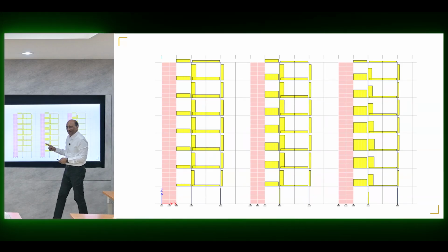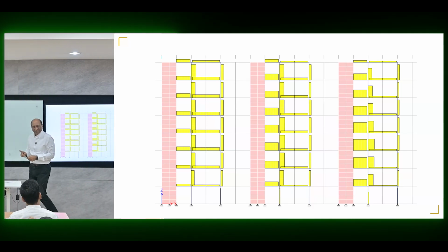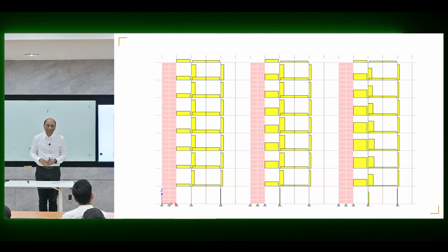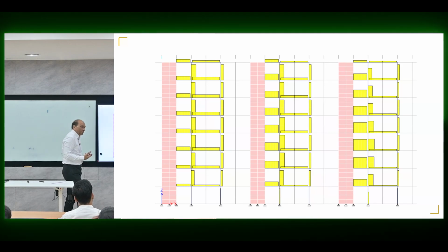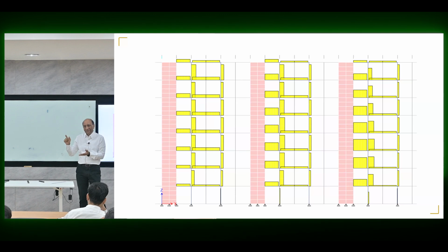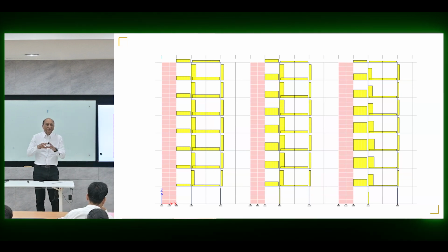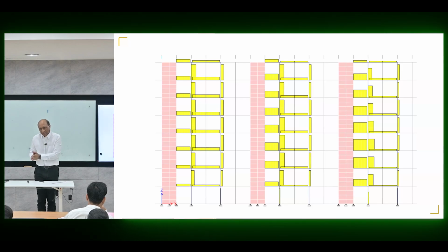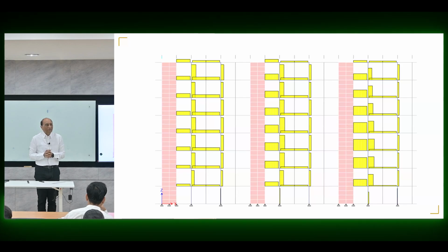And this is the problem, because when the shear becomes large, you have to design the coupling beam for that much shear. And very soon you will run out of the shear capacity of that coupling beam. So the shear capacity is now controlled by the size of the coupling beam and the concrete strength and the limits by the ACI. So invariably, even if you are able to provide a lot of reinforcement for bending moment, you will never ever be able to provide enough capacity in shear. So the coupling beam's first consequence is they will start to fail in shear if you let this happen.